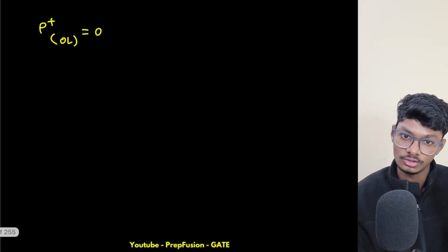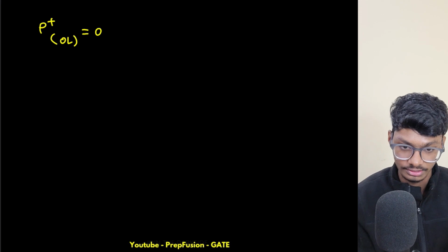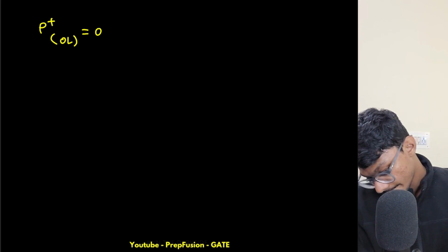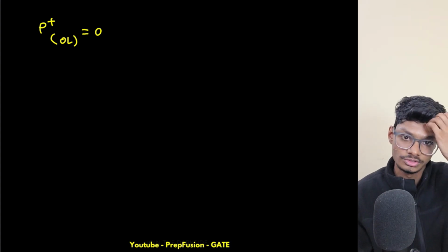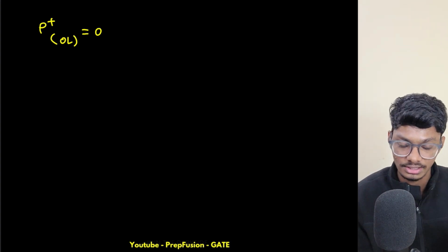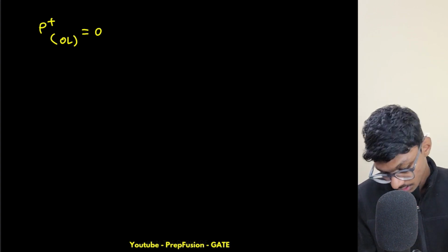Okay, you will study this in analog circuits, where you will study different types of filters, right? Also for all pass filters, my poles and zeros are in symmetrical locations. That's why my magnitude is constant, and the phase changes, right? So